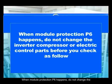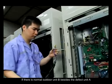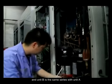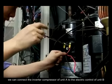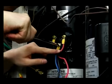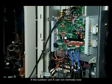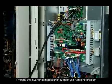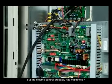When module protection P6 happens, do not change the inverter compressor or electric control parts before you check as follows. If there is a normal outdoor Unit B besides the defective Unit A, and Unit B is the same series as Unit A, we can connect the inverter compressor of Unit A to the electronic control of Unit B to see if it can start to run normally. If outdoor Unit A can run normally now, it means the inverter compressor of outdoor Unit A has no problem, but the electronic control probably has a malfunction.